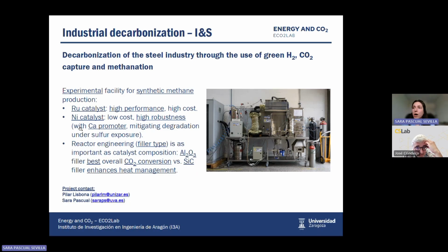However, the nickel catalyst is cheaper than the ruthenium one, and if you have this catalyst with promoters like calcium, we can mitigate the degradation and also limit the reduction in the methanation performance and in the catalyst lifetime.